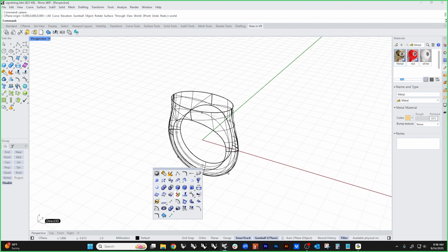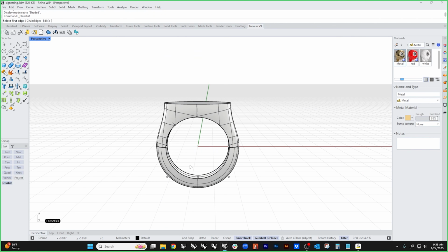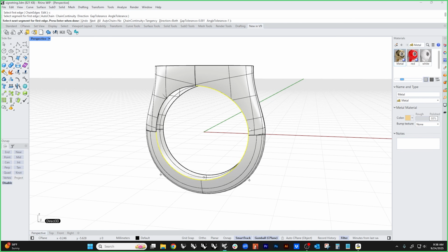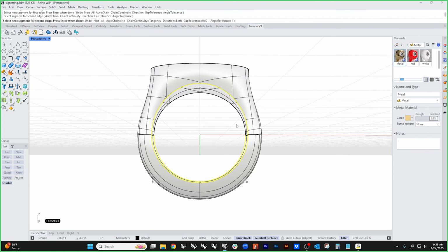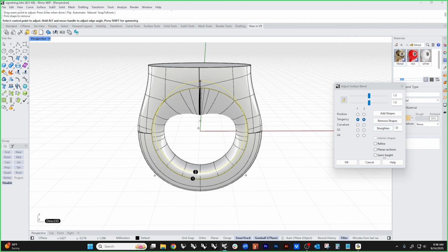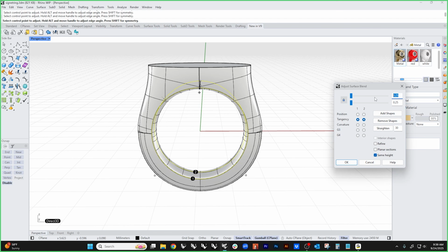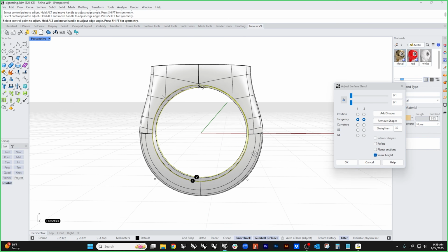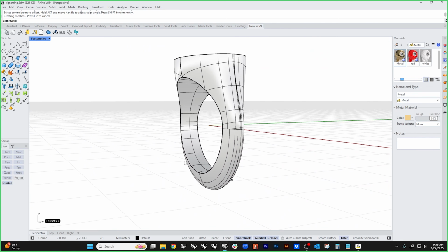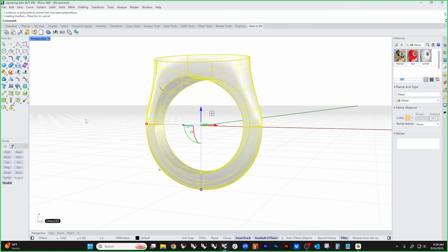So now we've got our final size in there. All that's left to do is just blend in the edges. We'll set that to same height. Drop that. We can even overblow this a little bit and go 0.1. That way it's just a hair sharper. It's got a little bit of crown in there, but the edges are still pretty sharp. Join it up, should be closed.